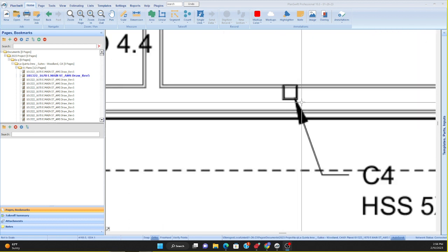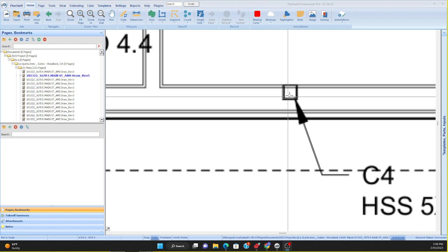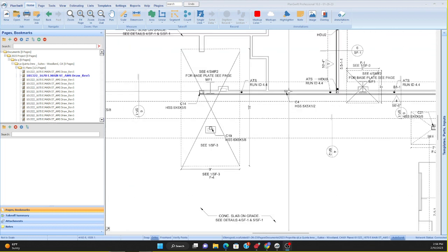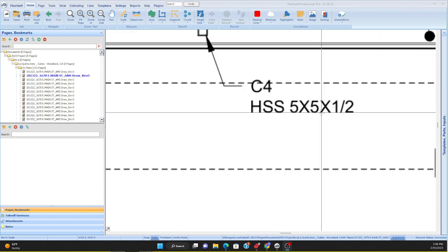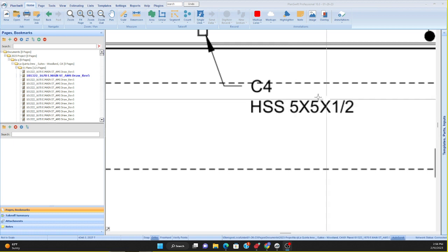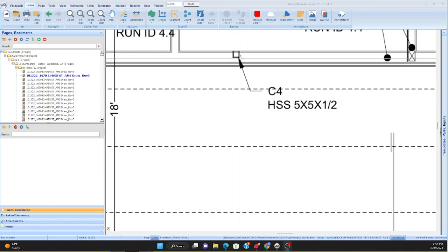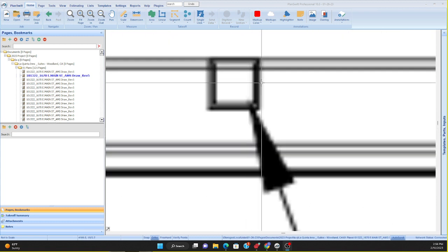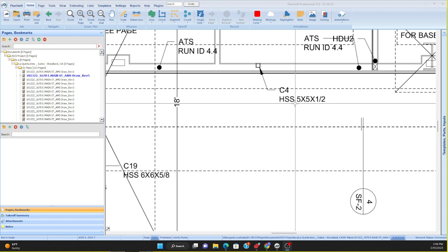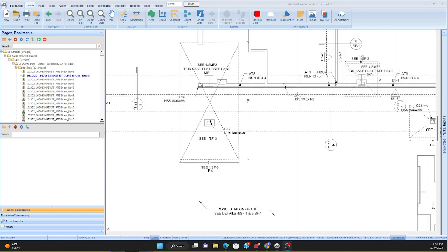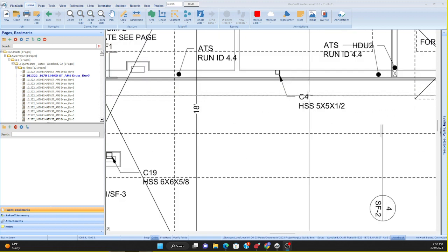See, it's not an X there, meaning it's hollow structural steel. Hollow, nothing on the inside. And these are the dimensions, 5 by 5, instead of like a 6-inch whatever stud. Well, this is a square, right? It's that same shape, and then the half is the thickness of it. So 5 by 5 by whatever. They call it C4, column 4.